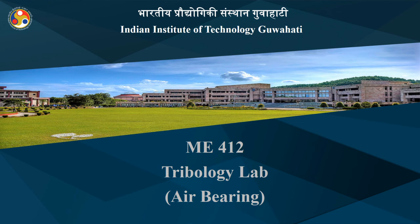In this, the shaft is connected to a high-speed AC motor. The shaft is inside a bearing which is made of brass. When the shaft rotates, it sucks atmospheric air, and due to the viscosity of air, pressure starts to build up. Due to this pressure, the shaft starts to float in the bearing.